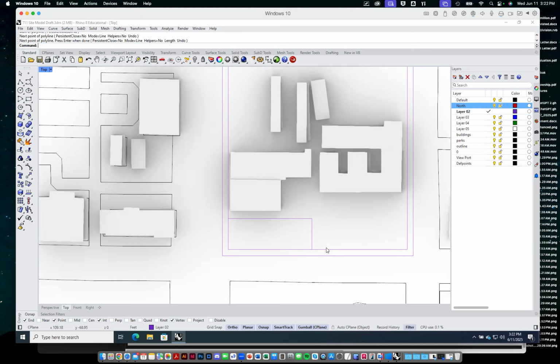It's based off that. Because this is an urban core, you can build pretty close, but you just have to have that fire rating, right? Because you don't want a fire to spread before the fire department goes in and tries to contain it. And then there'll be the 6 inch there. But what'll happen, you know, 3 hour on the side, right there, that's fine.